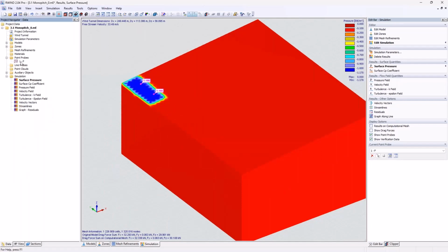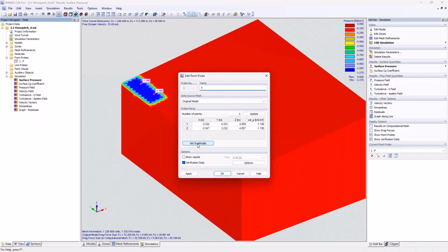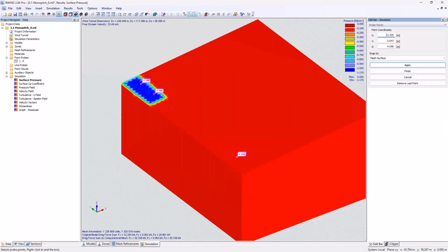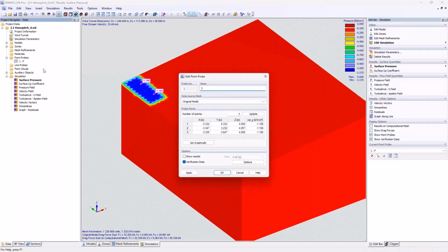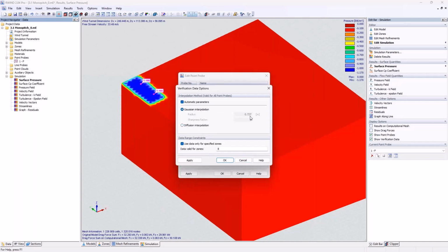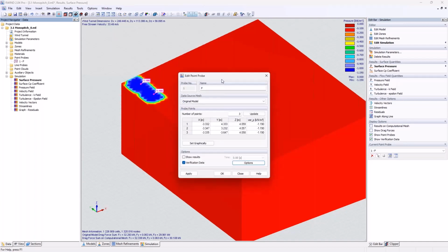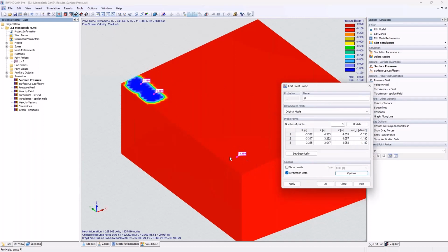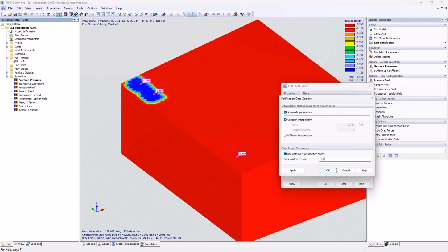We will now introduce some more points. I will enter 1 more in the other area, say okay. We go in there, and it already has the latest value. If we now switch to the Gaussian interpolation with a radius of minus 0.72 and hit apply, we will see that nothing is done in here. Keep in mind, we restricted it currently to 8. We can also restrict it to 8 and 9, and then we see that the interpolation is done in a bit different way to the diffusion. With diffusion, it is using a wider area, and Gaussian is using the automatic parameter defined in here.